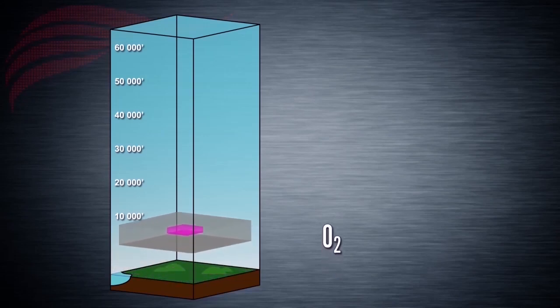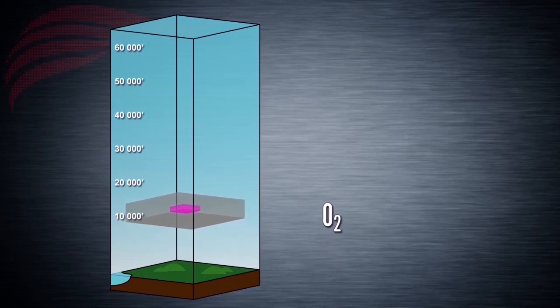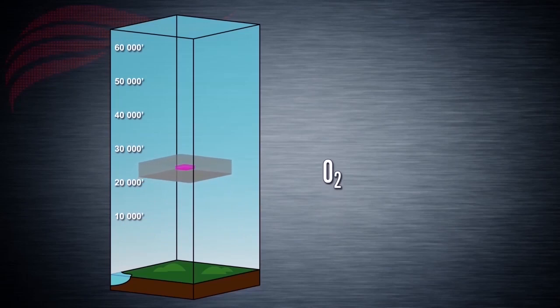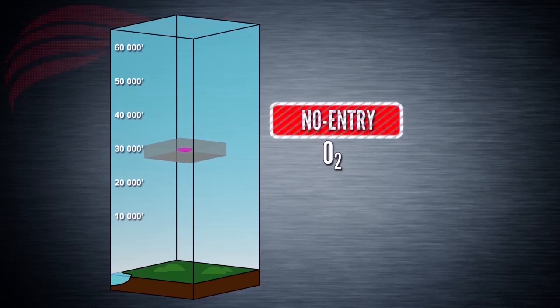Therefore, the concentration and pressure of oxygen also reduces to about 30% of sea level value at flight level 300, which is only 63.8 hectopascals. Naturally, this amount of oxygen is not sufficient to sustain life and permit cellular respiration. In simple terms, people would suffer from oxygen starvation if exposed to these pressure conditions, in a condition known as